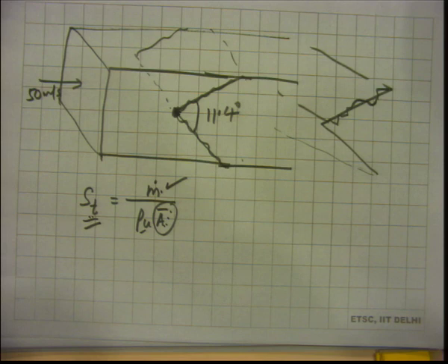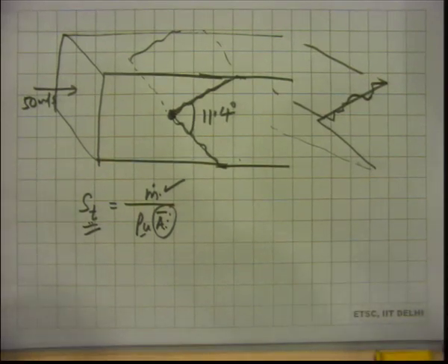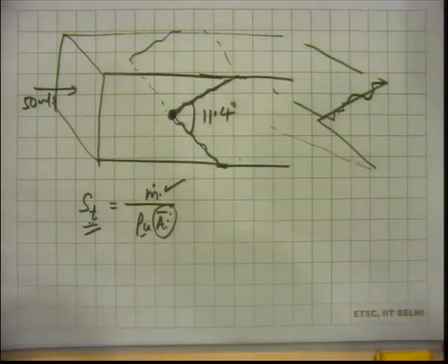So what I was saying is that we have the rod for some reason, isn't it? What does the reason seem to be? It's anchoring the flame, isn't it? And if you don't place anything here, then you just have a flowing mixture of fuel and air. Of course, you can ignite it, but if you ignite it, do you think the flame will remain at one place? No. Maybe in exceptional situation, but not usually, right? So the rod is actually stabilizing the flame.